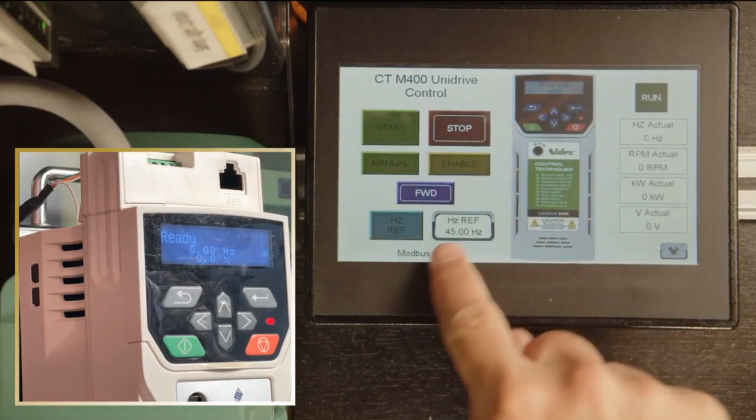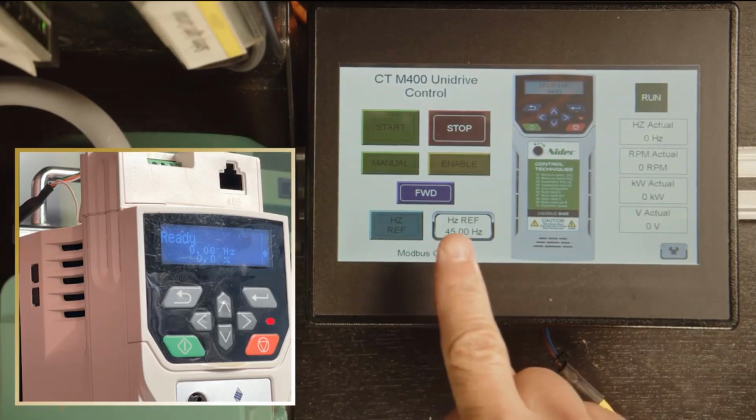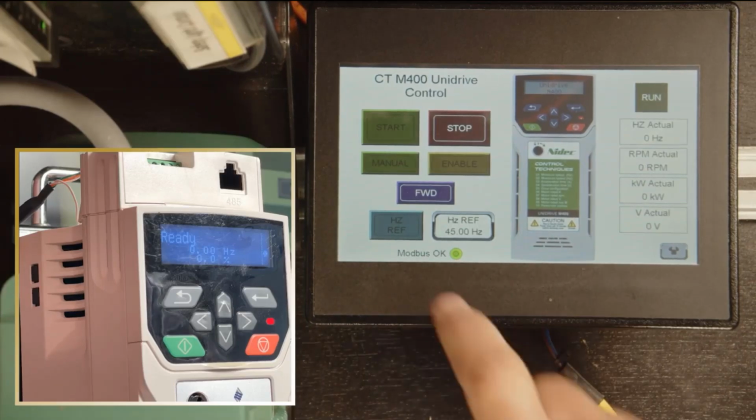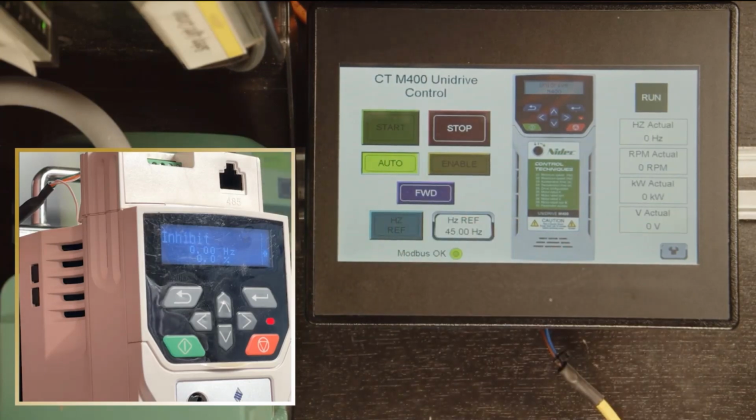So here are those operators that are, for the most part, tied to the control word, different bits within the control word. We have also got a word which is the speed reference that we can write down to the drive. We have got our Modbus OK indicator, which is green. Everything's good. So if we switch from manual mode into auto mode, which means the OCS is in control, you